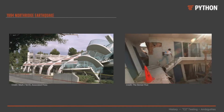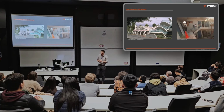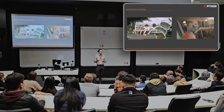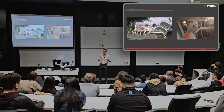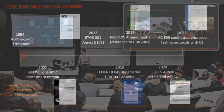So this whole part of our industry really kicked off in 1994 after the Northridge Earthquake in California. Prior to this, designers were using monotonic test data in uncracked concrete to design post-installed anchors. I suspect everyone in this room will intuit that this is going to be unconservative in many seismic scenarios, and there were many failures in this earthquake of post-installed anchors. This triggered a lot of work in this space.